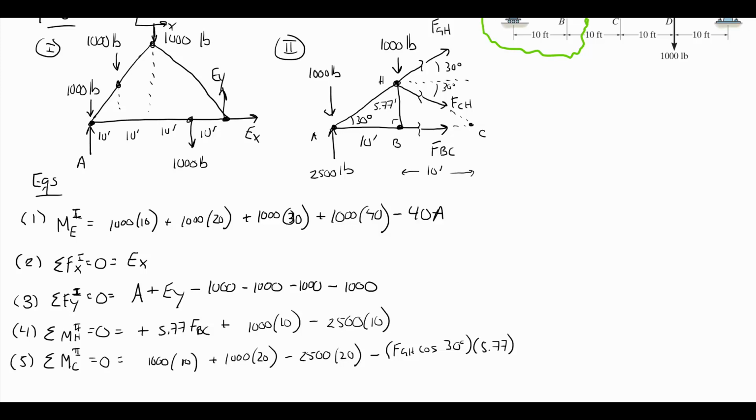And note here, my base units are feet and pounds for force, feet for distance. Now I have a vertical component as well, minus FGH sine 30, and it has a perpendicular distance, that's the horizontal distance to C, of 10. All right, so in this equation, I have only 1 unknown, GH. So I'll be able to solve that.